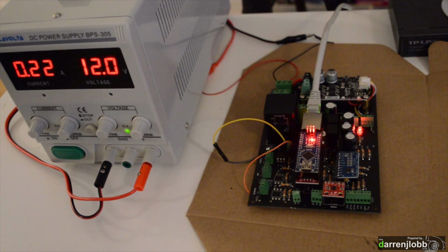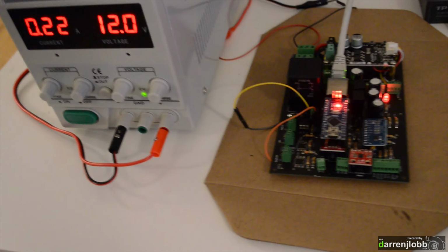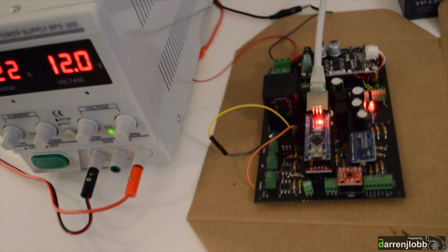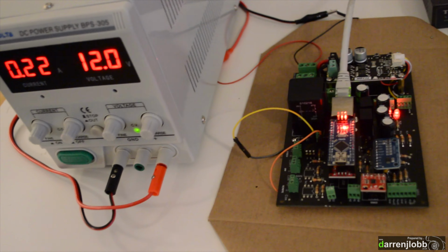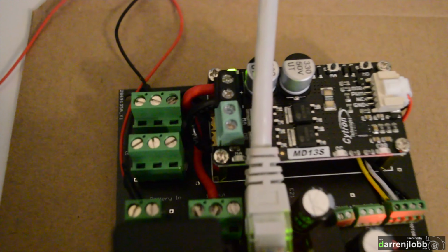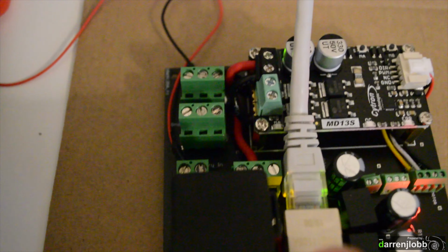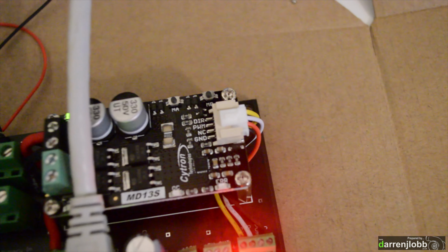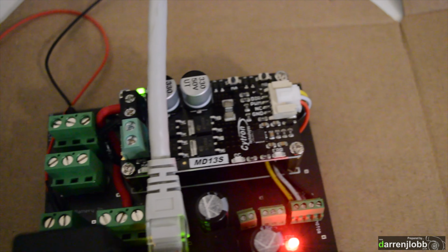So I've got it all together now. Just put it on the bench and hooked up a power supply to it. I've already uploaded the sketch from the Arduino software on the computer, and set a few settings in there which I'll flick across to in a second. So just basically put 12 volt to our battery connections and ground. We've also got 12 volt out from the relay active side, so the powered on side of the relay, for power for the motor driver board, and also an additional ground for that. Hooked up the output for the motor controller also.